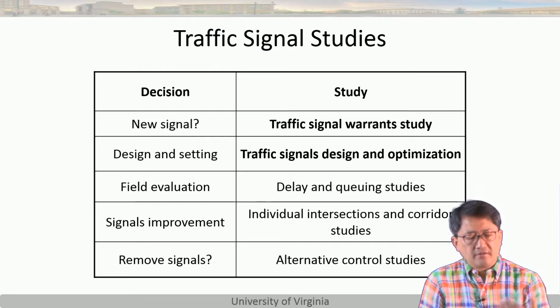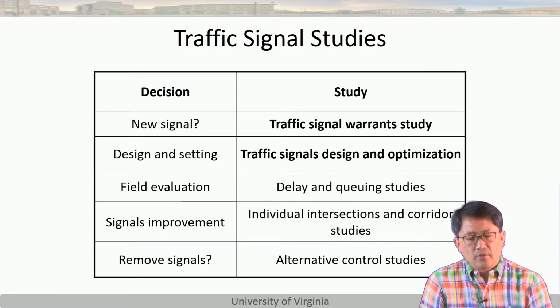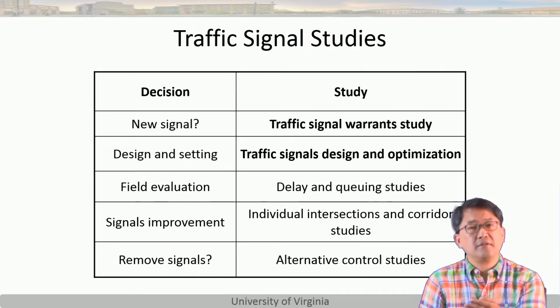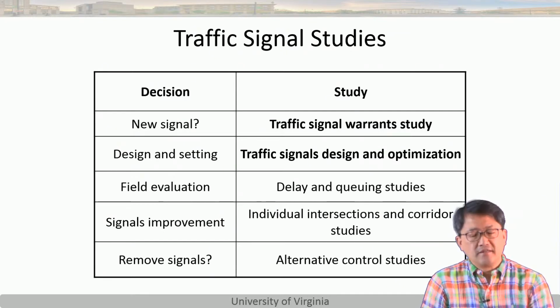Field evaluation, all of this is basically common sense knowledge. We can look at the queue length, which is one easy way to evaluate conditions. Looking at it as a corridor, you can do probe vehicle trial runs, so you just drive through the area. And nowadays, people actually use GPS. It can tell you at the end of the run which signal is getting the progression, where you stop, and whether you can make some improvements. Things like that can be easily done.